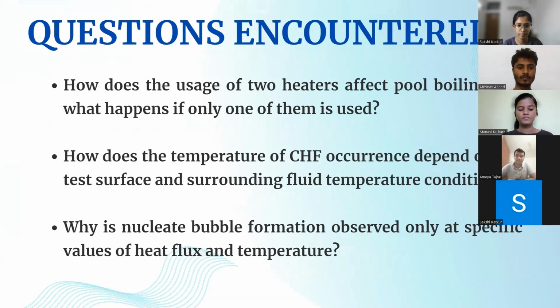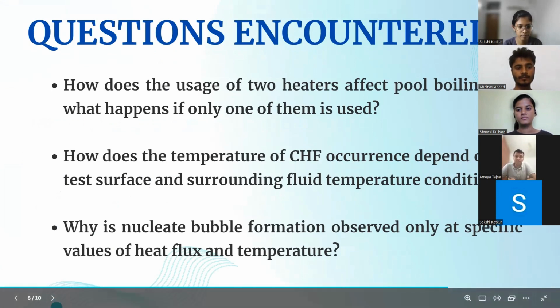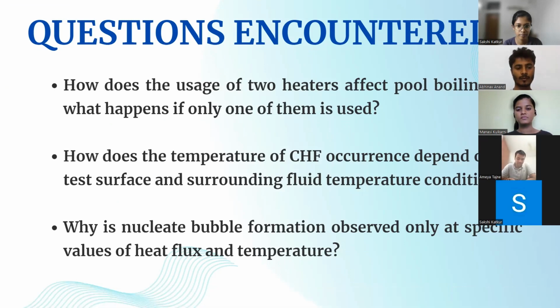While studying and researching for this experiment, we encountered majorly three questions. The questions are, firstly, how does the usage of two heaters affect the pool boiling and what happens if only one of them is used? We anticipated that copper has some nucleation sites, and when the cartridge heater is inserted it helps in the formation of bubbles.